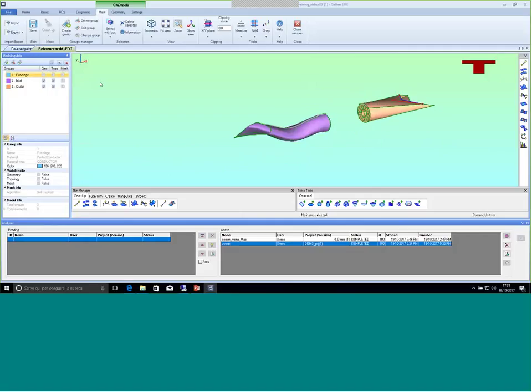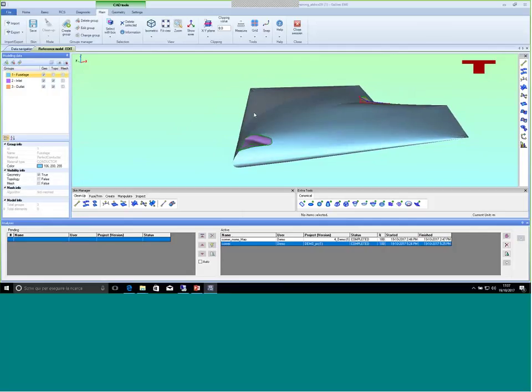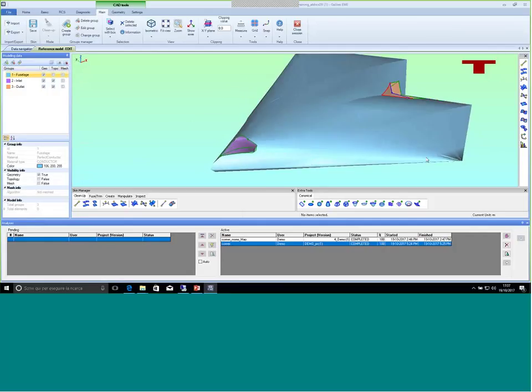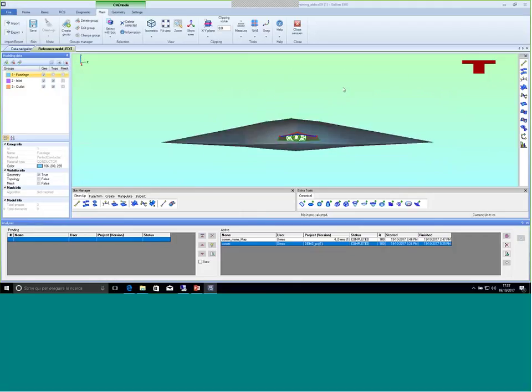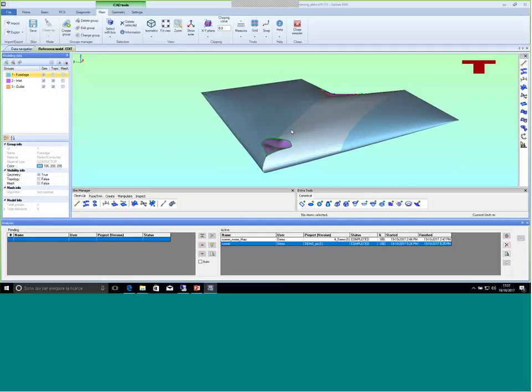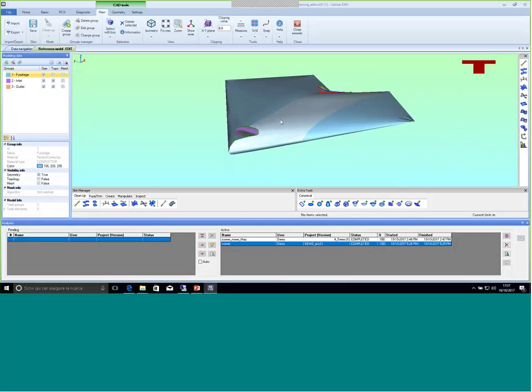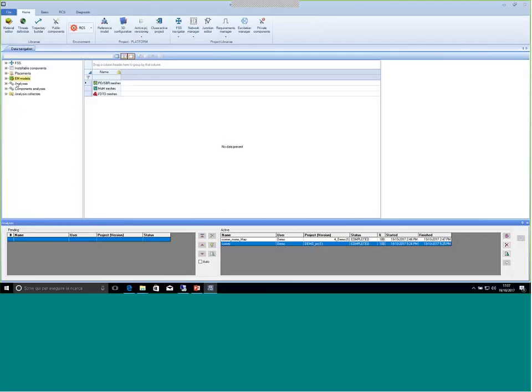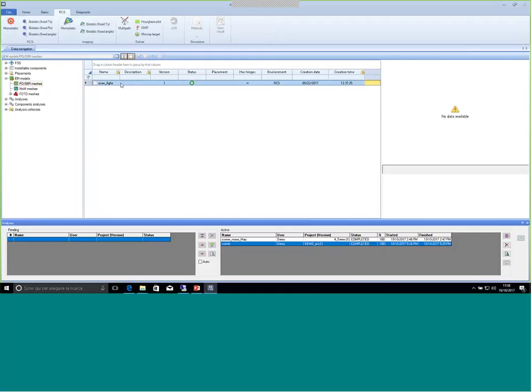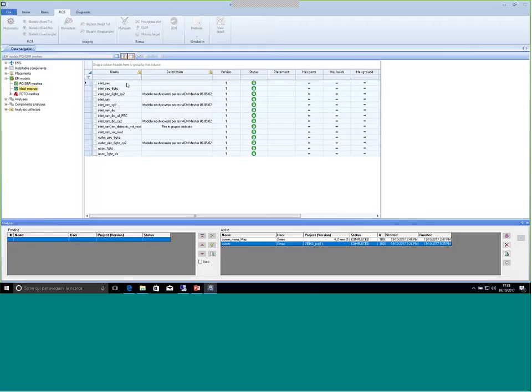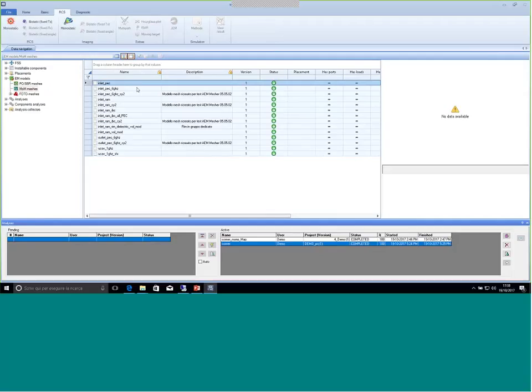My approach in this case is going to be to simulate the external fuselage of the aircraft with an asymptotic method, and the inlet and the outlet, that are complex shaped structures, and sometimes also with some radar absorbing materials installed inside, and then combine all those results for computing the overall contribution. And the inlet and the outlet will be simulated with a full wave method. So for this reason, I have generated 3 different models. One model for the asymptotic solvers, and 2 different models, one for the inlet and one for the outlet.